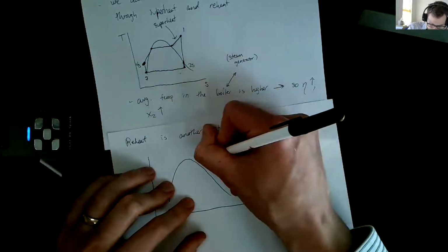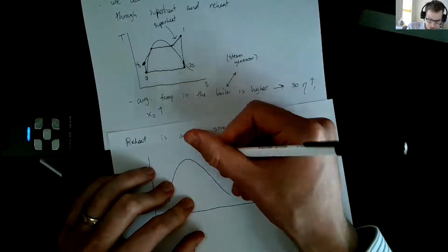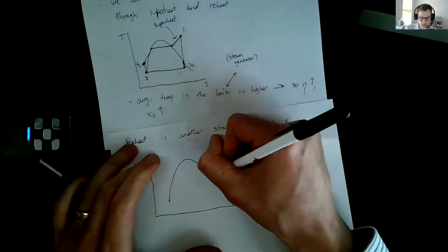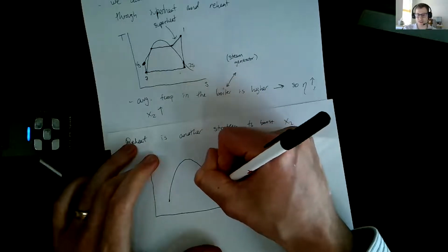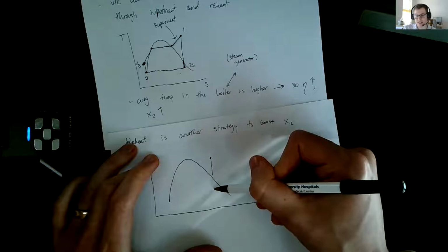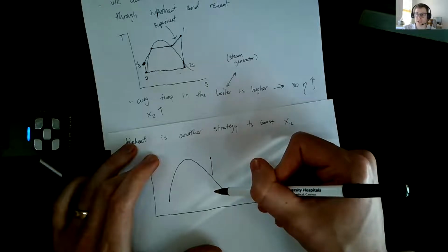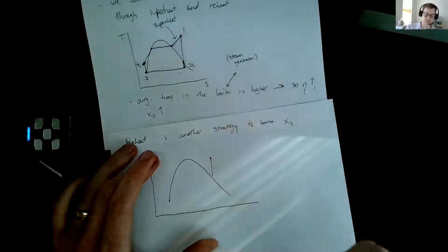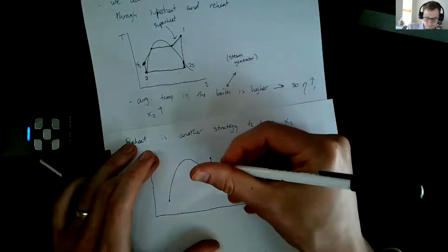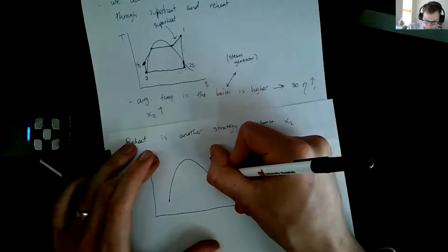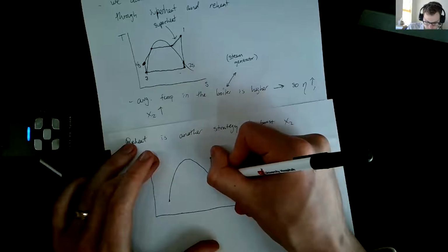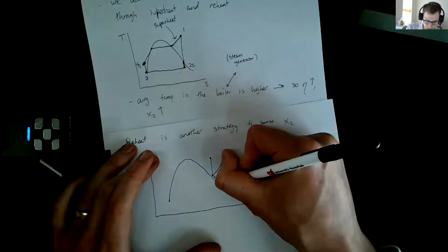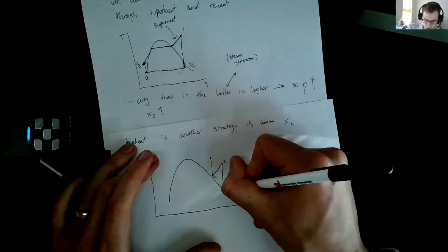All right, so we'll put state 1 over here, so we'll do some superheating. Okay, and then we'll come down to state 2, except instead of going all the way down to our low pressure and getting into a quality that might be less than 90%, I'm sorry, my fist is blocking this. Instead of getting all the way down to something that might be less than a quality of 90%, before we get there, what we'll do is we'll pipe it back into the steam generator. I'm going to draw you a diagram in a second so you see how this works. And heat it up again. So this will be state 2. This will be state 3. And now we'll run it through another stage of the turbine and come down to state 4.